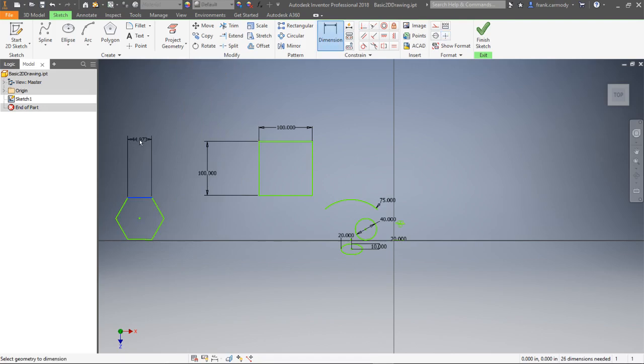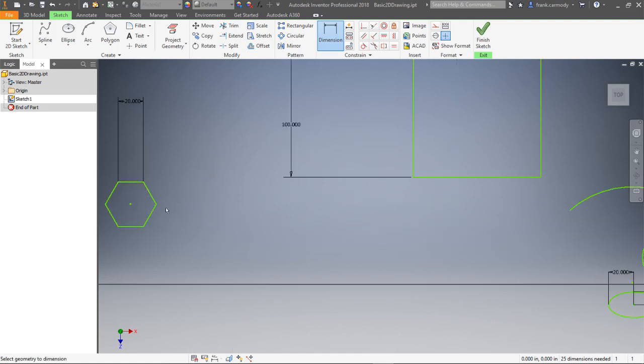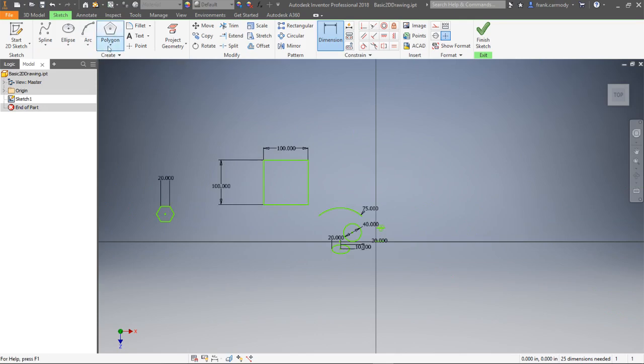Yes. So basically what I had was I had all the constraints on it. Basically I was going over the constraints. It wasn't letting me select the lines properly. Okay, so I clicked dimensioning tool. I clicked on one of the lines, and basically these are made to have equivalent length sides, right? So that's the definition of them. So these n-sided figures in Inventor, basically by setting one side, you're setting the length for all sides at one time. Okay? All right, so that is the polygon.